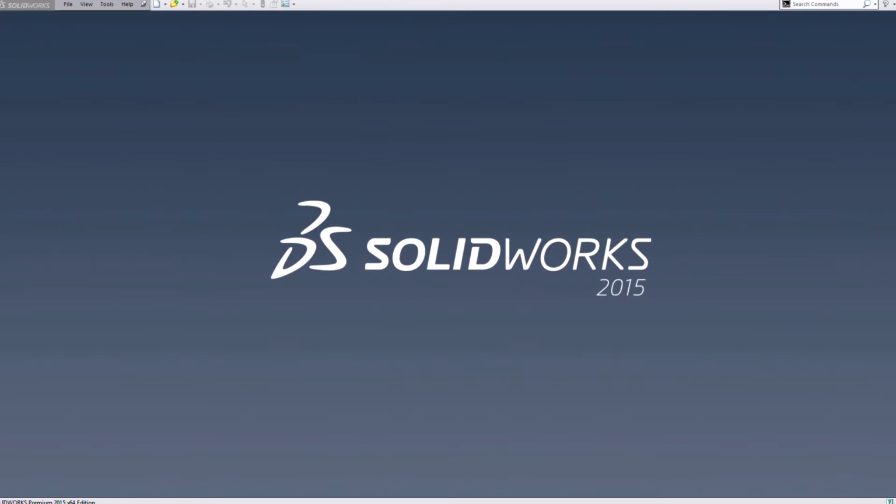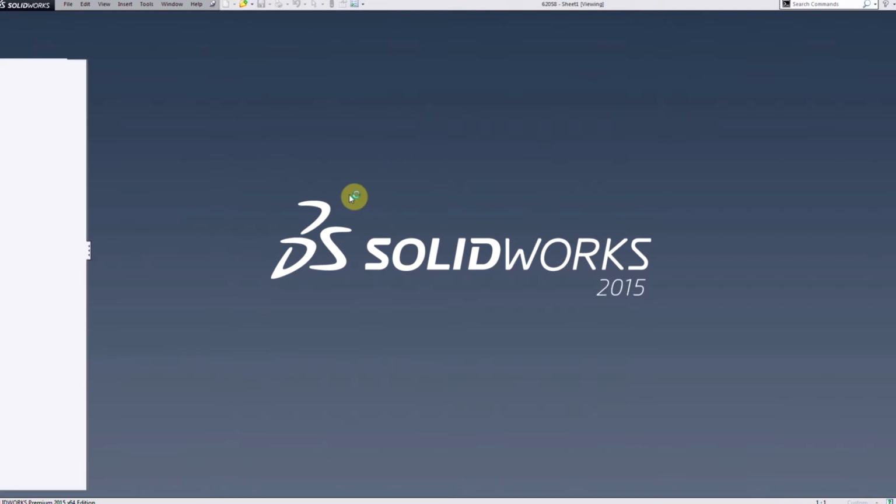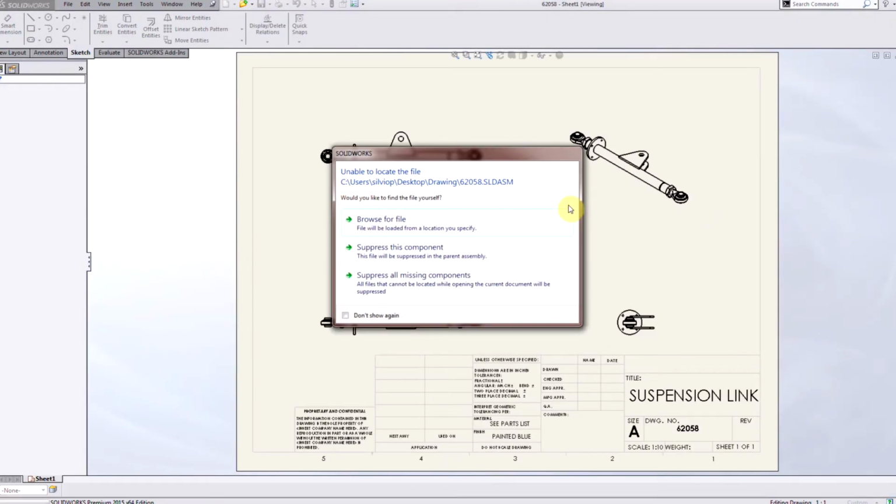In today's video I'll be showing you how we can create a detached drawing and discuss the benefits of this drawing type. Anyone that uses 2D drawings most likely goes through some review process where the file needs to be sent to multiple people. One of the struggles with this is that if you want the end user to be able to have some level of editing power for the drawing, we can't just send the drawing itself. One of the things that we'd run into is if we open up that drawing without the reference files, we get this message where it wants to browse to specific file sets. Well, in this case, we want to just be able to send the file and give the user some level of editing.